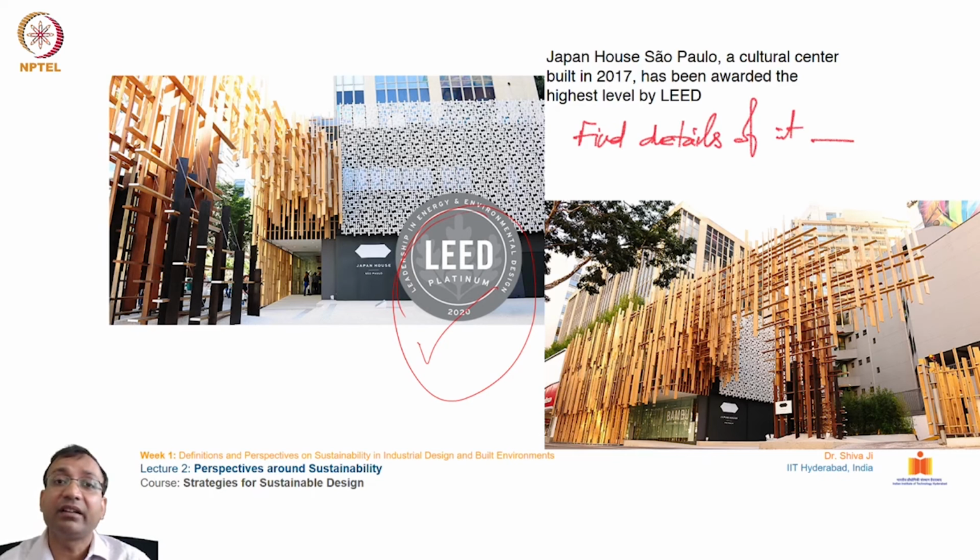First of all, it's creating an air buffer. I'm sure you can understand that. By this crisscrossing, puzzle-like structure, it's trapping air, restricting the air movement on the surface of this building. And air is an insulator material. So in turn, this is going to restrict the direct falling of the sun on the surface of the building, on the interiors, on the glass surfaces.